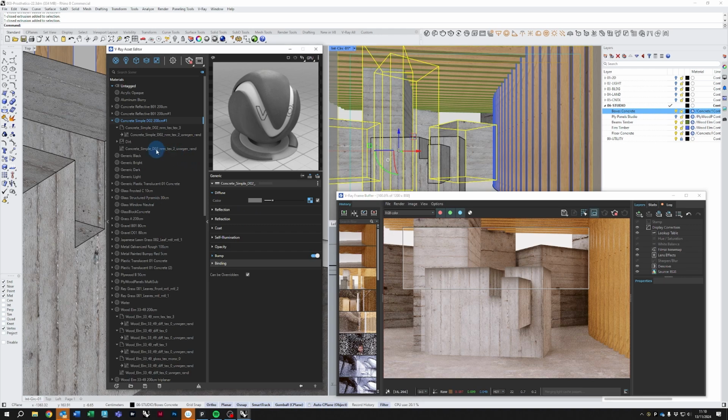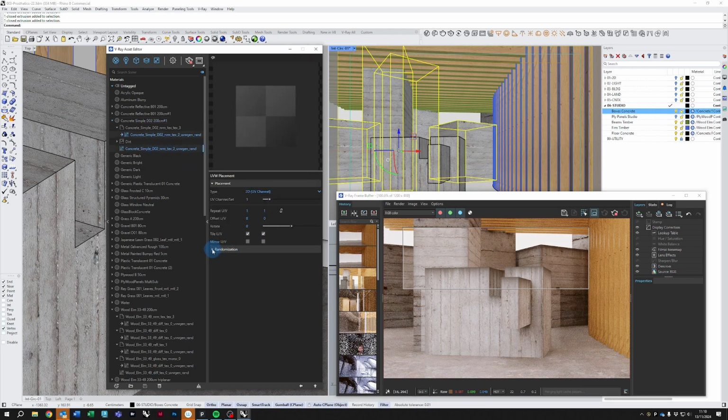The other thing I want to point out, again done by default from Cosmos, but it also has stochastic tiling ticked. And it again has the UV rotation in steps of 2, so it will flip by 180 degrees. And the other thing that it has set here is it will offset in the y direction.